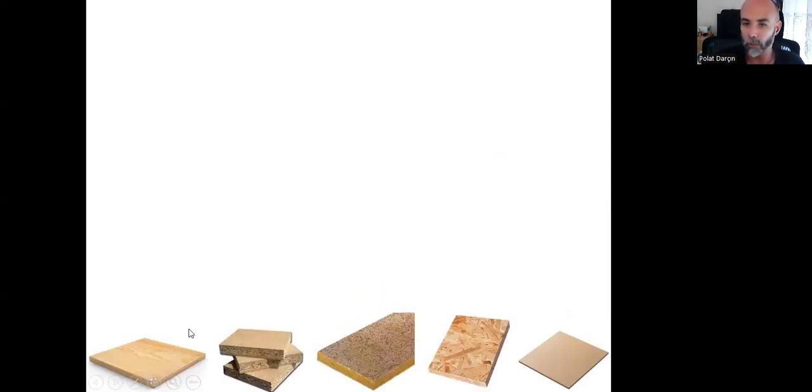The best ones can be plywood, HDF, or cement chipboard. We need to avoid the synthetic binder chipboard, sunta. We don't want that. And we can use oriented strand board as well for our floor surface, and we can have one or two layers on top of each other.